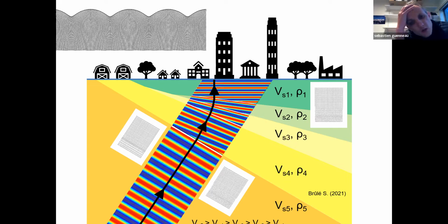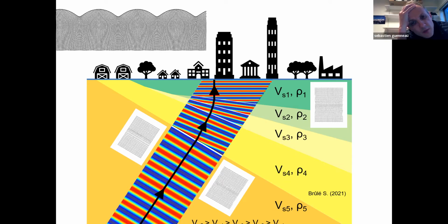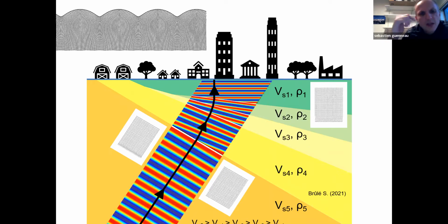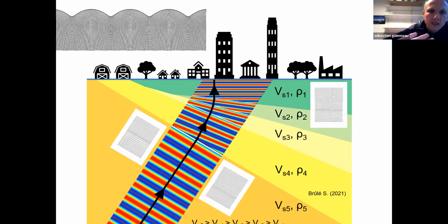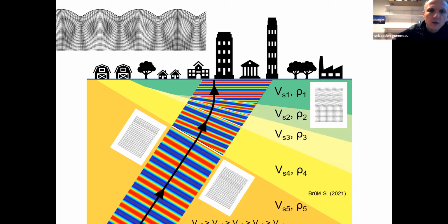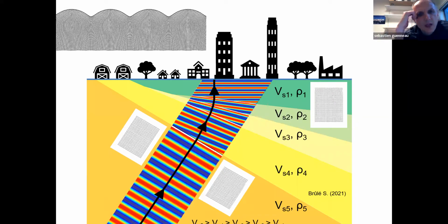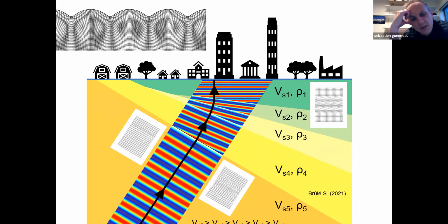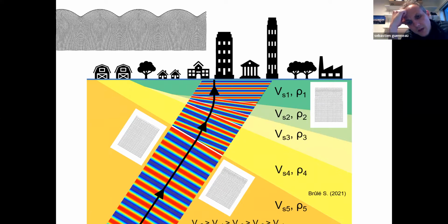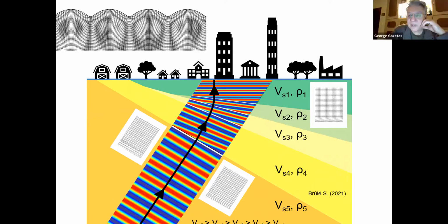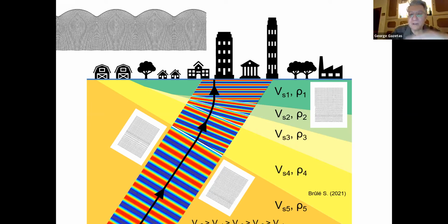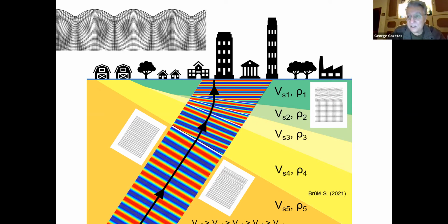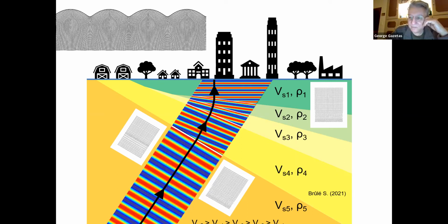And in fact, do you think you will also have a coupling between anti-plane shear and in-plane waves? Let us imagine that your incident wave is purely in plane. When you reach an interface, will it remain in plane, or will you have a coupling between out-of-plane and in-plane? As long as the layers continue in the horizontal direction without changing, of course, they will remain in plane.